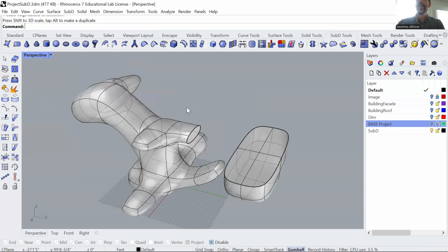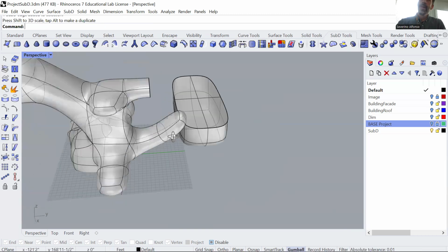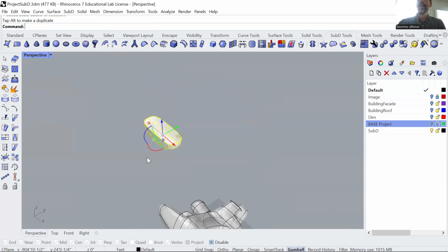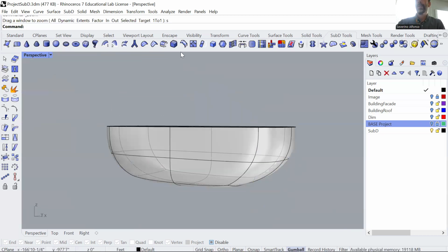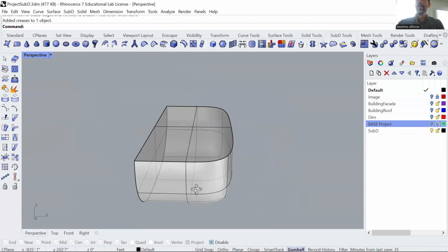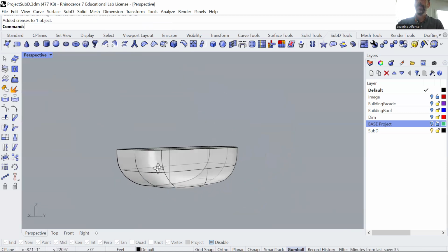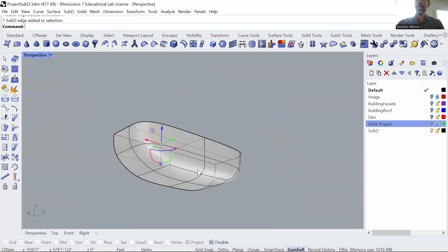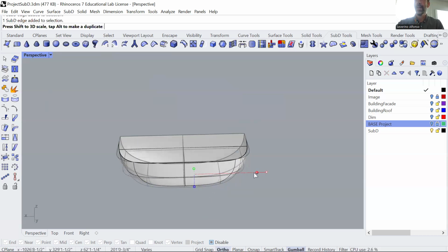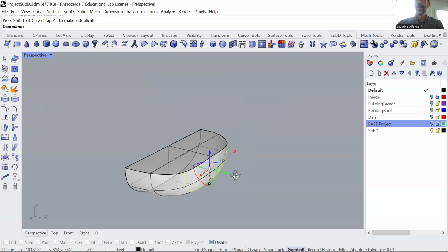And then you say it's still not there. Maybe we do a crease on the back as well. So let me take that here. And I'm going to select crease and also these elements here. No, so it starts looking more interesting. Maybe now we make the front even smoother. Again, I'm pressing Control Shift and continue selecting and scale that. So that could be a nice thing.